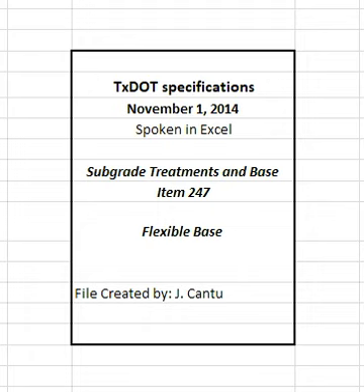Return unused department-owned recycled materials to the department stockpile location designated by the engineer unless otherwise shown on the plans. The use of contractor-owned recycled materials is allowed when shown on the plans. Contractor-owned surplus recycled materials remain the property of the contractor. Remove contractor-owned recycled materials from the project and dispose of them in accordance with federal, state, and local regulations before project acceptance. Do not intermingle contractor-owned recycled material with department-owned recycled material unless approved.